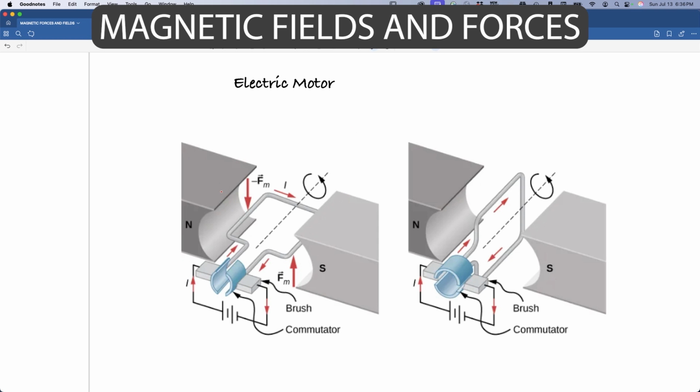This is one of the strongest forms of a magnet, and that's why it's used. And also, the pole faces are not flat, they're arc-shaped in such a way that the two arcs form a part of a circle. The idea is to have a radial magnetic field here. So that means if I were to draw, the magnetic field would be along the radius.